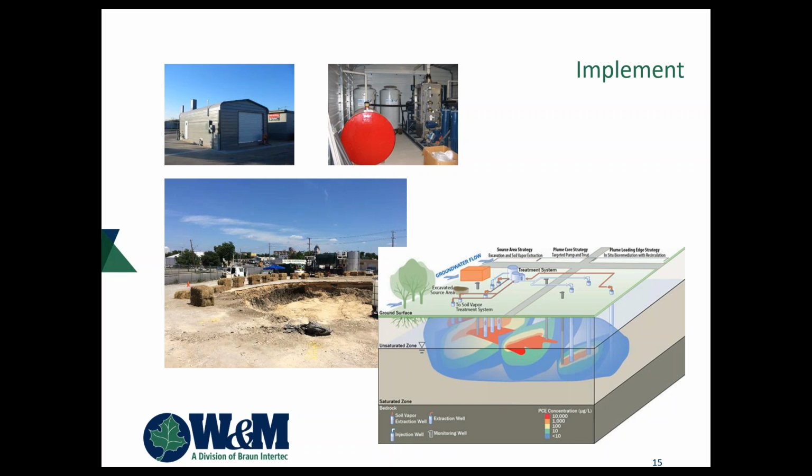And that big spreadsheet that we showed earlier. Have you had anyone that has ever done the $50 million projects? I haven't been a direct part of it, but I've been adjacent to some very large thermal projects where thousands and thousands of amps worth of high voltage power were fed to electroresistive heaters that were placed into the ground to cook the soil to a couple hundred degrees and bake all the water and contamination directly out of the ground, to the point that the down gradient monitor well temperature a year later was over 150 degrees Fahrenheit. Wow, that's crazy. Sometimes it's the right answer.